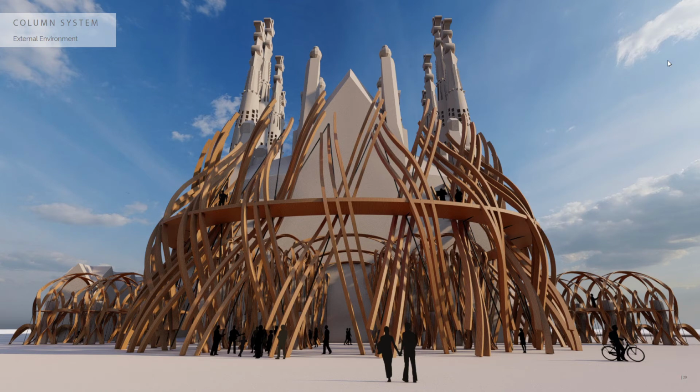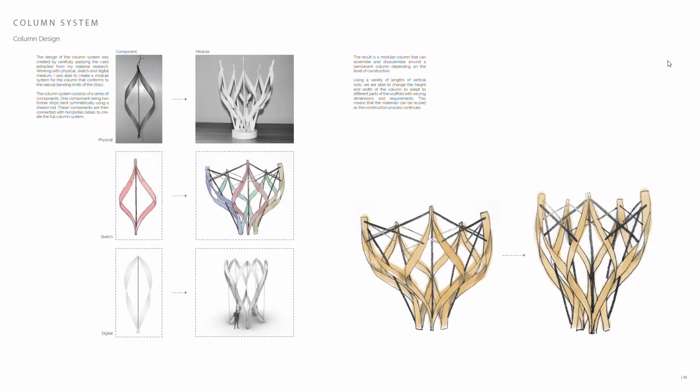The design of the column system was created by carefully applying the rules extracted by my material research. Working with physical, sketch, and digital medium, I created a module system that conforms to the natural bending limits of the strips. The module consists of a series of components, one component being 2 timber strips bent symmetrically using a shared rod. These components are then connected with horizontal cables to create the full module. By extending or reducing the length of the rods, the column height can be adjusted and then reused in different areas of the construction site.